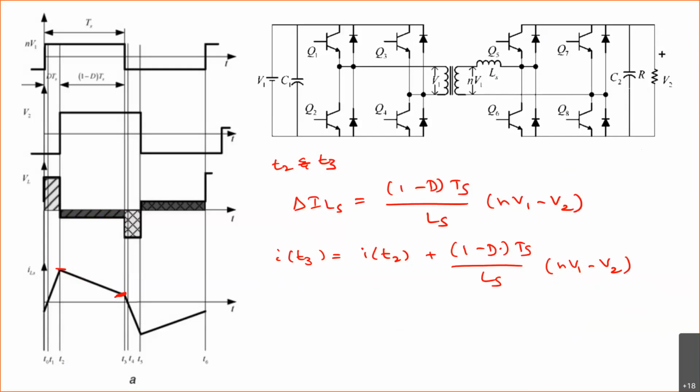So next, we have other modes. We have now completed from 0 to the off cycle period TS. It is divided into 3 parts. In the first part, the inductor current touches 0 from its negative value. In the second part, from 0 to where it reaches its peak value.